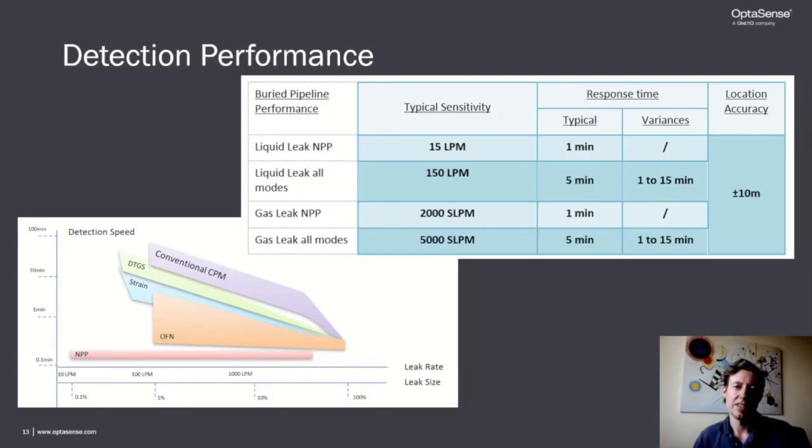For the smallest leaks, the only indicator may be a negative pressure pulse, at the instant pipeline integrity is lost. As such, we consider this to be the most valuable signal, and it is run independently. With this, we can provide near instantaneous detection with the characteristic V-shape acting as an arrow pointing directly to the source. The stated 1-minute response time takes into account the amount of time required for a trained operator to acknowledge, investigate, and confirm the alert.